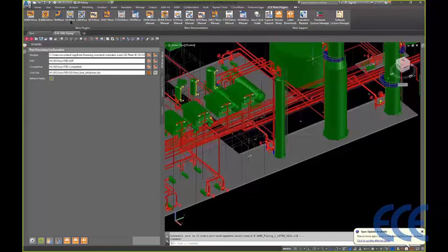The first tab is just basic setup. So we're asking you where your models are going to reside. I'm just working with the out-of-the-box sample project for Plant 3D. The next one is going to be your work in progress folder. So this allows you to run your ISOs through Plant 3D and then go ahead and put a copy of them in this directory. And once they're in here, this is where you can open up the ISOs, double check to make sure that they ran okay.